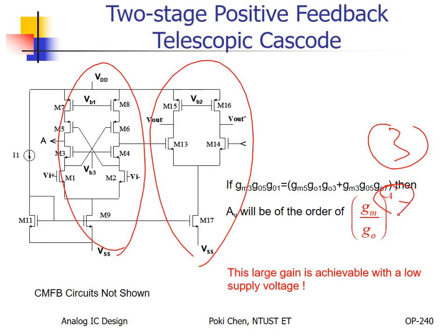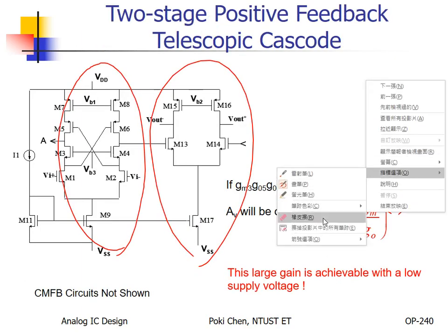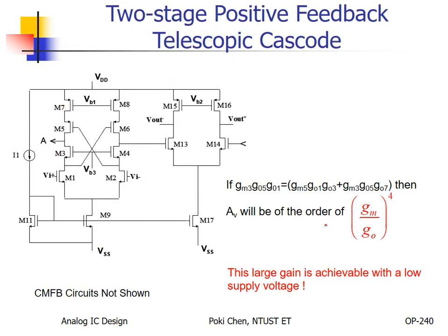So it means what? For the traditional one, they don't have this. That is the only difference in structure, with this cross connection or not. For all the others, they are about the same. I cannot say exactly the same. The major challenge for such kind of negative impedance or cross connection is that it is hard to stabilize the Q point.